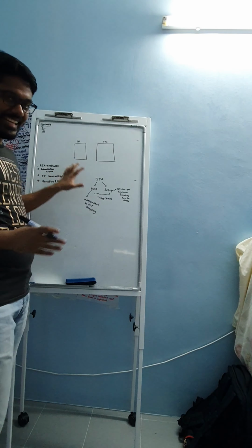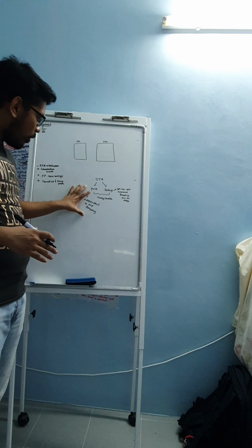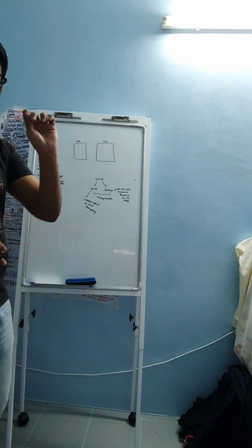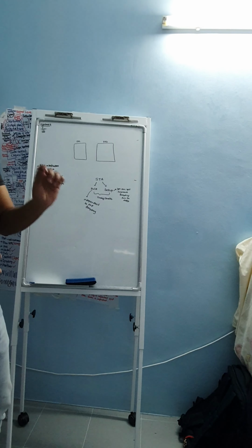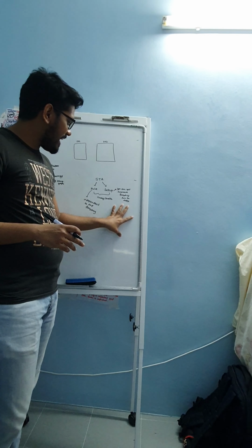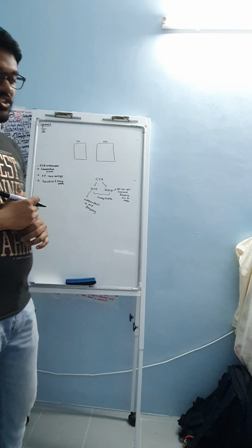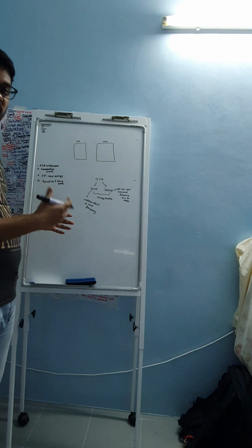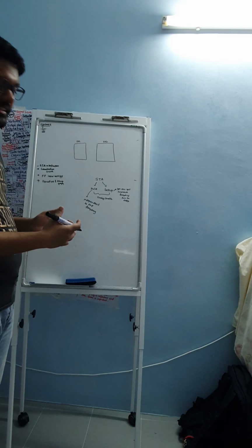I'm going to explain that later, but for now I would say hold is checked at the same clock edge, so the same clock, and setup is checked on the next clock edge. That is the reason you are seeing the big difference over here.